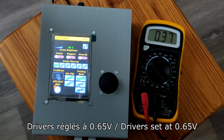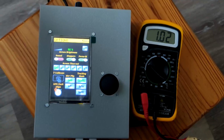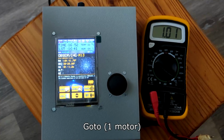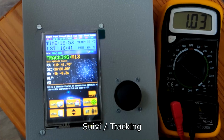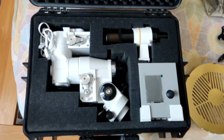When I added a fan there was a little bit more consumption, so let's take a look at that. I decreased the drivers just a little bit more, to 0.65. There is a slight increase in idle, and when you are in tracking or GOTO with 1 or 2 motors, it's always about 1 ampere. I am now with the mount at full speed and better cooling, and the rDUINOScope is consuming just 1 ampere. This is a power consumption reduction of 20 to 30% compared to the default values.